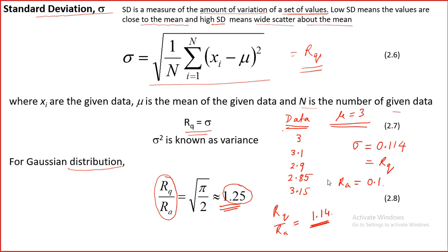surface features or textures. So when we talk about texture of a surface, we include many pieces of information, not just RA or RQ. Okay. So that is how we define the surface texture. But in the majority of our cases, we will use RA as the parameter, and sometimes it is possible to use just one parameter like RA if the manufacturing process the surface has gone through is the same. So in that case, whatever variation there is will be the same in the 2 surfaces, so we can use RA as